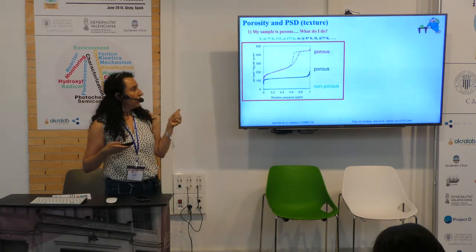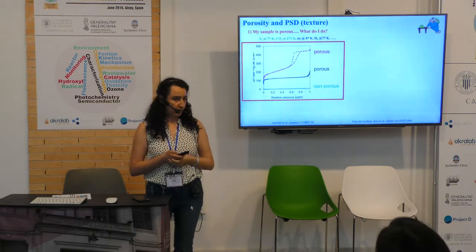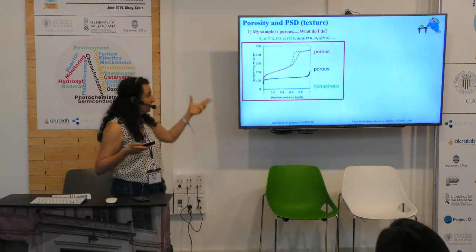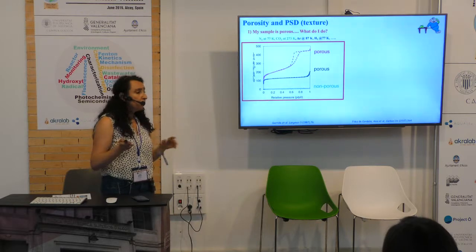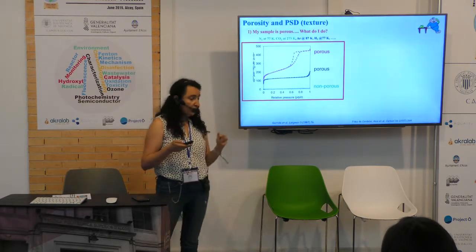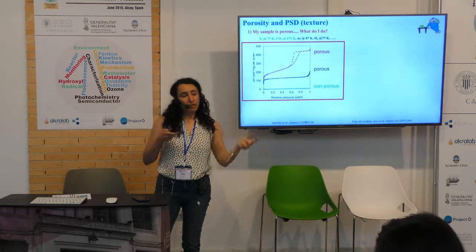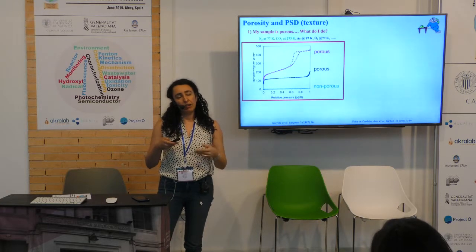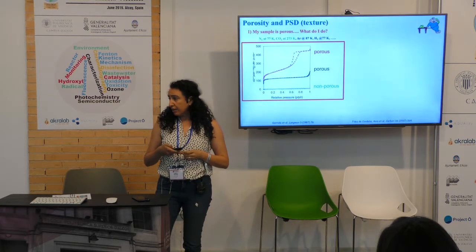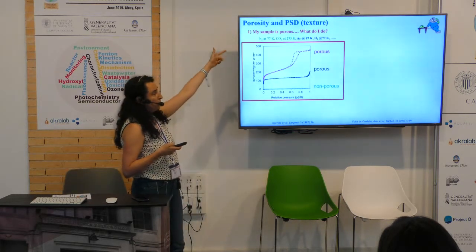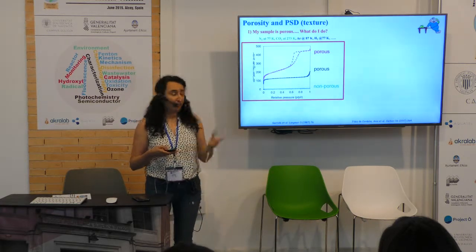So then you have a catalyst, and you think your catalyst is porous. So what do you do? You want to analyze it. So the first choice is, what gas do I take? Because IUPAC recommends many of them. Well, it depends on whether you are in the States or in Europe, because you can use nitrogen at 77K or argon at 87K. But in Europe, argon at 87K is very expensive, although now things are much better due to the presence of cryostats. Mostly all the people use nitrogen at 77K, but in the States it's easier to get argon, so it really depends.